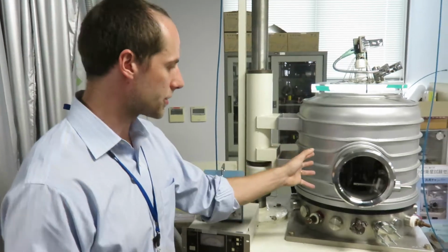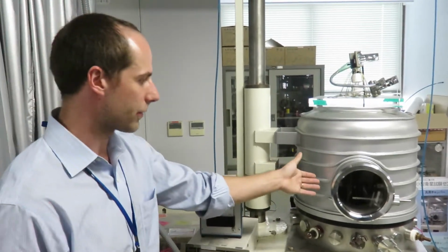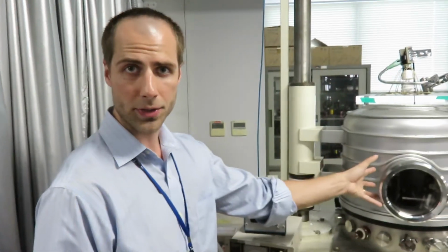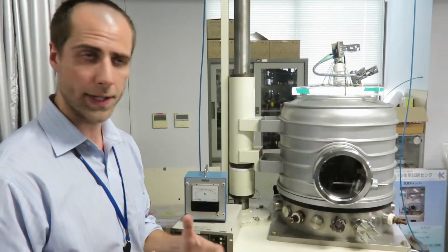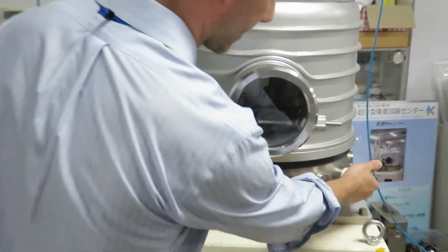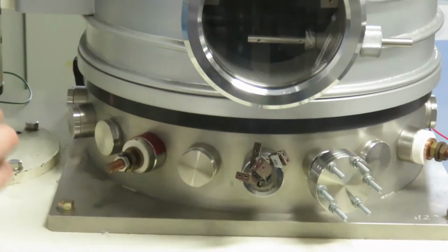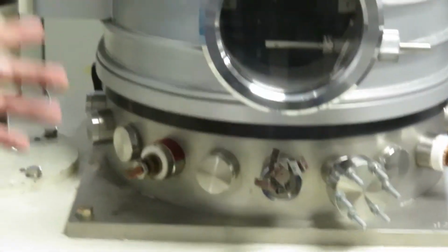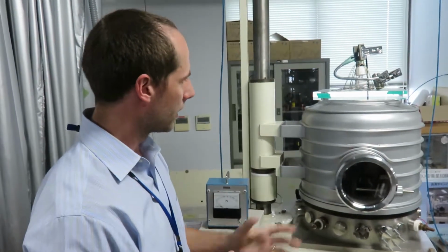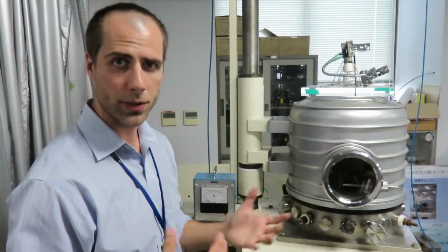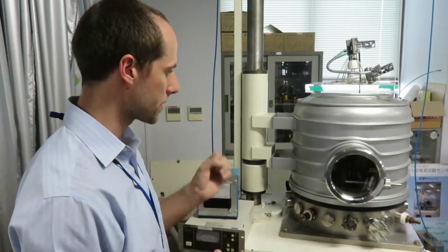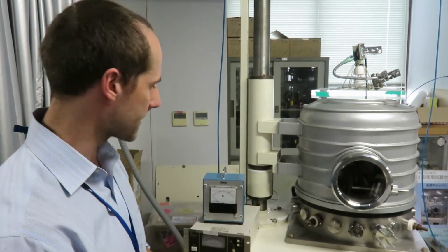And we use this chamber for a number of things. For example, I think recently there was a test on a micro thruster that we're building for our satellite project in this chamber, because we have high voltage and high current feed-throughs to simulate a high voltage thruster. But we also use it for dust experiments. And in that case, we install some sort of plasma source, an electron source, or some other plasma source to charge the dust and make measurements.